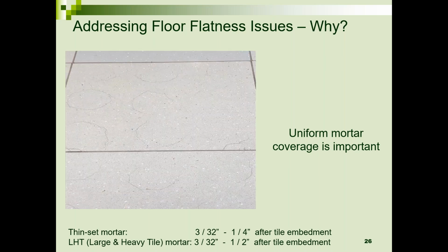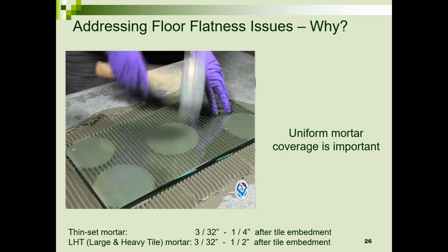And what types of problems? Here's the extreme of misapplication of the mortar, thick and thin. We see spot bonding. How do I know it's spot bonding? Because you could see the cracks, the circles where spots of mortar were put down, and the mortar was too thick. It shrunk, and it cracked the tiles. So there's your spot bonding, creating cracks in the tiles, and that's your extreme in too much mortar used underneath the tile. So spot bonding is a no-no with the cementitious mortars.